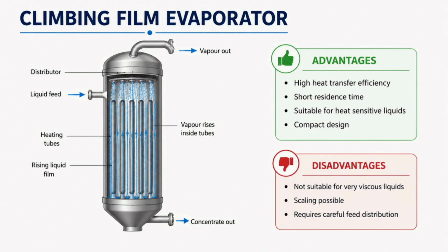So the contact time between the liquid and the heat is very short, making it suitable for heat sensitive drugs. For example, fruit juices and antibiotic solutions can be concentrated safely here. So one advantage is high evaporation efficiency. Another advantage is it mainly reduces the thermal decomposition due to short heating time.